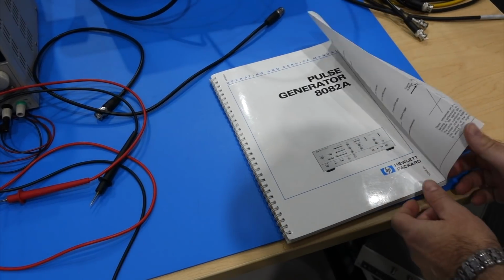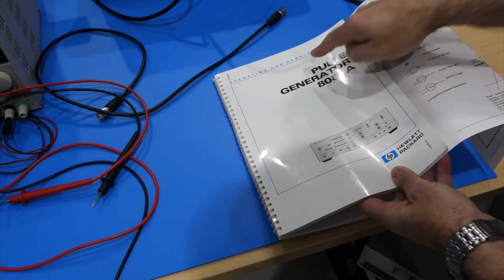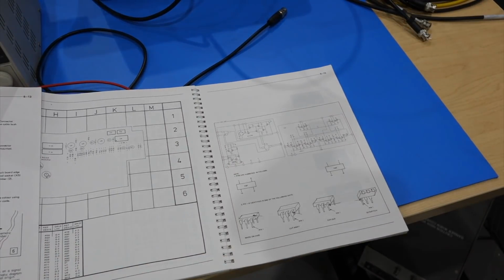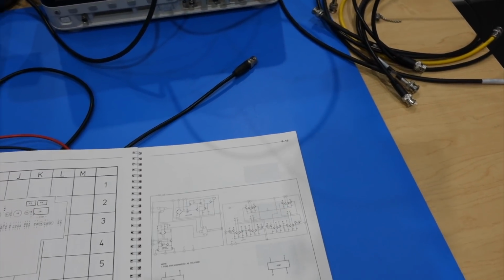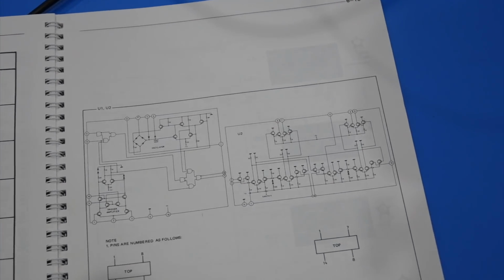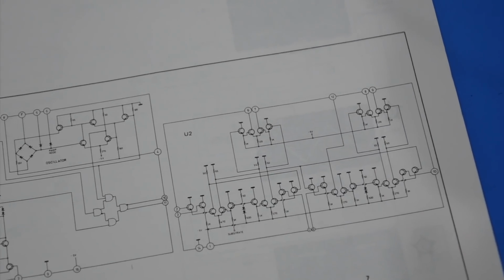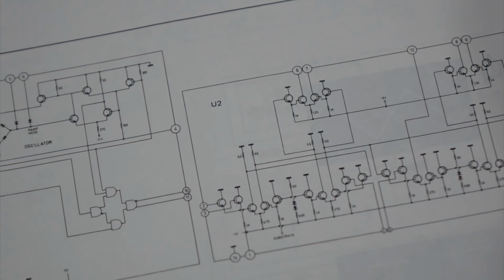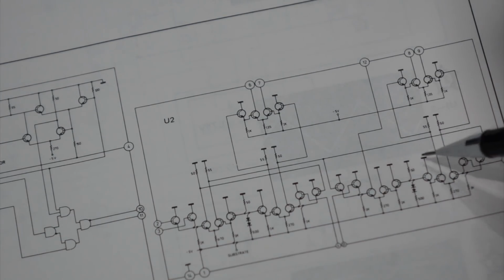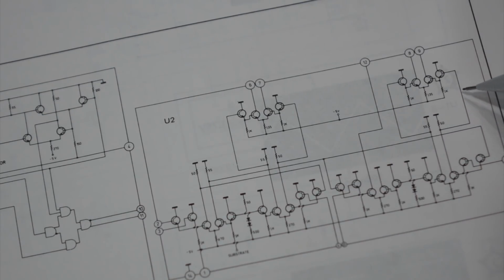Alright, so the plot thickens because in the meantime I've been able to get an original manual, and in the original manual you can actually have readable schematics of what's in the original U2 circuit, and you can see that I'm on the right track. You see the gates internally, they have the 50 ohm termination and the 270 ohm tail resistor on the emitters, but on the output stage it's different.